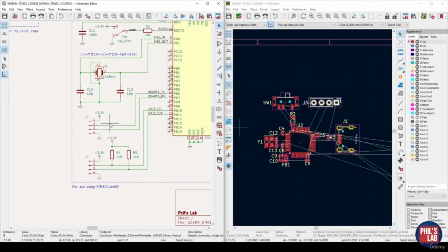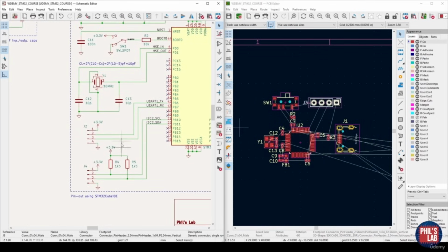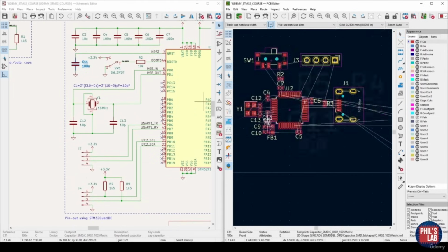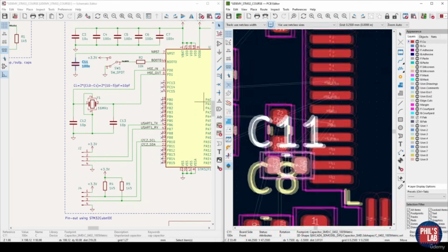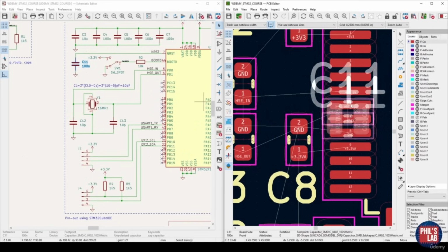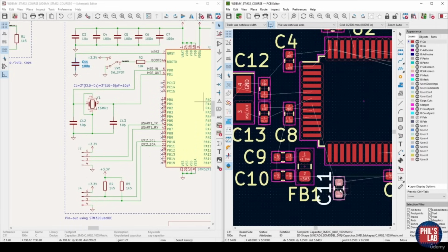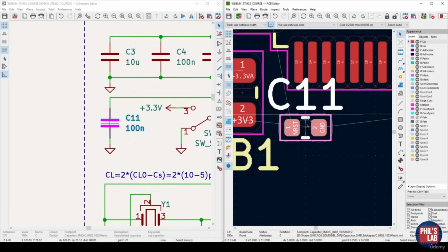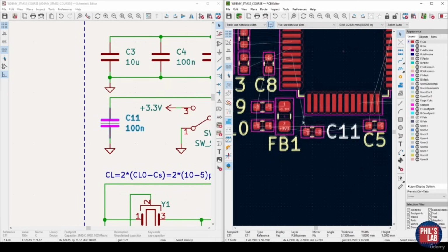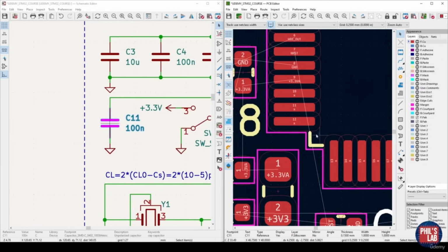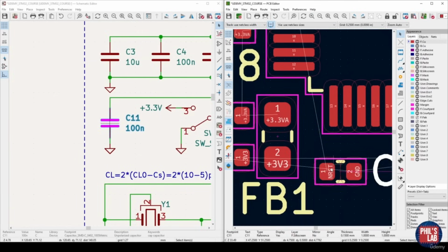Then we still have these connectors over here before we need to do the power supply. And we can't, of course, forget this bypass capacitor for the NRESET line. And this is going to be a bit cramped because we have the HSE-in connections up here and reset over there. But NRESET isn't that critical, and it doesn't have to be placed anywhere close. So what I'm thinking, I'm going to place it somewhere down here because I can simply then later route out over here, down here, and into the NRESET line here, for example.